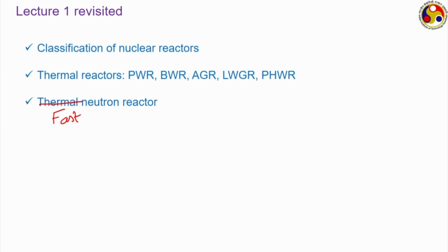So, there is no moderator, and because of very high energy density we need a coolant with high thermal conductivity, and accordingly liquid metals like commonly liquid sodium, and in certain situations liquid potassium or a sodium potassium mixture, are used as the working medium. Here also you need a secondary, sometimes even a tertiary loop to get the actual power cycle going.